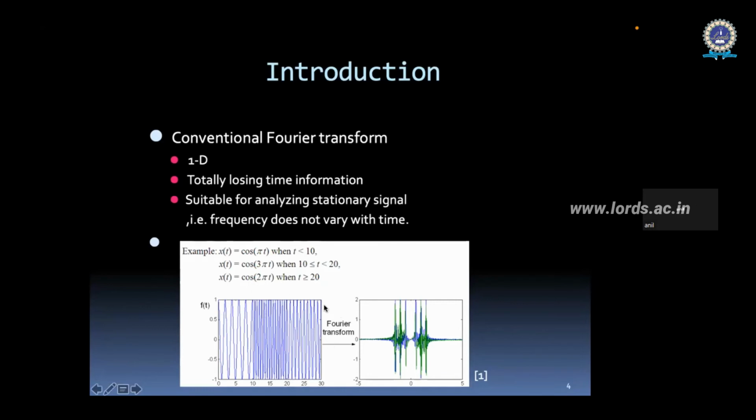It works, but everything about the resultant spectrogram depends on your window size. If you take the proper window size, you will get a proper spectrum, but finding the proper window is very difficult. But luckily, speech is not fully non-stationary.